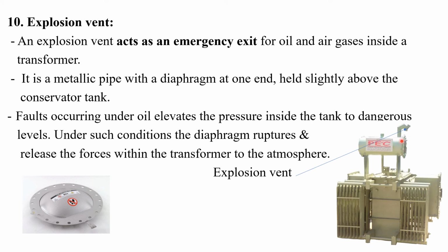transformer oil will sometimes flow to the environment through this explosion vent. Then we can understand that some severe fault occurred in the transformer main tank. So the explosion vent helps to identify that some fault is very severe in the transformer. So we can check that fault. Okay.